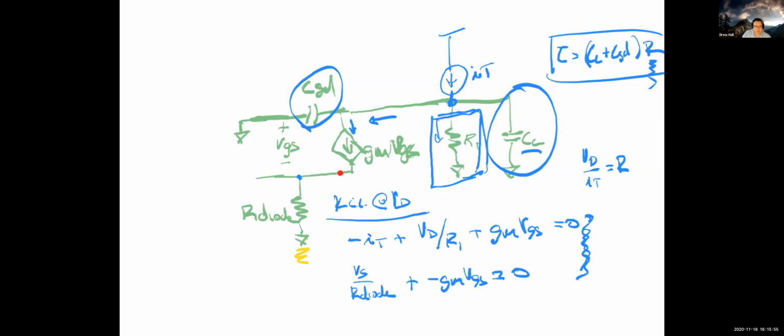I have a question, Professor, about just the value of CGD, because we know that it's equal to COV using the equations in one of the previous lectures. But COV has units of femtofarad per micrometer. But the units of a capacitance of a capacitor is in farads, not farads per micrometer. Yes, everything that you said is correct.